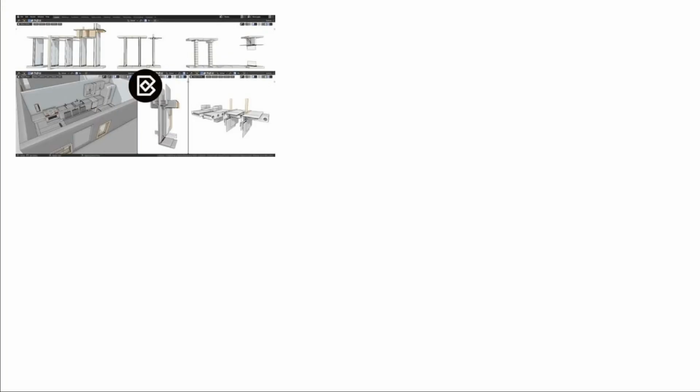The BlenderBIM add-on started around 2019. We had designed a small building in Blender, and it came to the point that we needed to start documenting and assigning BIM data. So we had two choices. We could either rebuild the model, which was fairly detailed and had some complex junctions and geometry, in a tool like Autodesk Revit, or we could build all the BIM functionality we needed back into Blender. So we wrote an experimental script on option number 2, and we figured that it took about 83 lines of code to export Blender geometry to IFC.